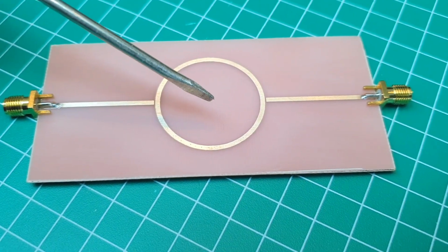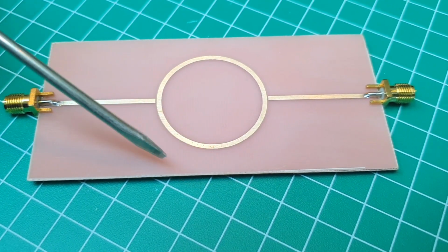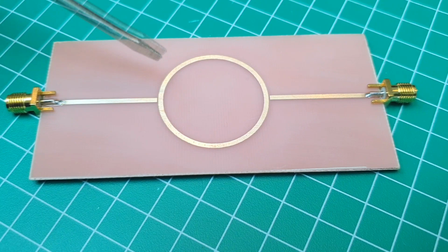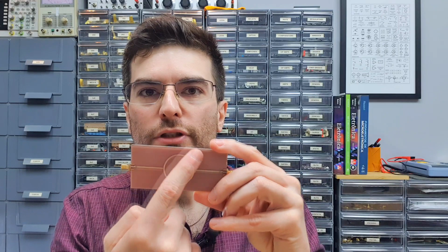I calculated a radius for the ring that creates a 100 millimeter circumference. The total physical length of the ring is 100 millimeters. And here is the key observation about this method, and actually about the other methods also. 100 millimeters is the physical length of the resonator. If we calculate a resonance frequency for a wavelength of 100 millimeters, we are going to get a resonance frequency. But when we perform the measurements, we are going to see the resonance frequencies are much lower than that.